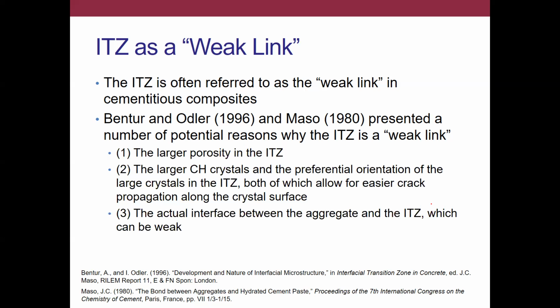Okay, and so that interface can have some type of mechanical bond that we can characterize, particularly if you have a rough or angular aggregate. Then there's also the chemical aspect of that interface to consider. What is the potential for actual chemical bonding between the cement hydration products and your aggregate? So that interface can be weak. It depends on if there is chemical bonding, and it depends on the texture of the aggregate for mechanical bonding. So there can be a few reasons there.